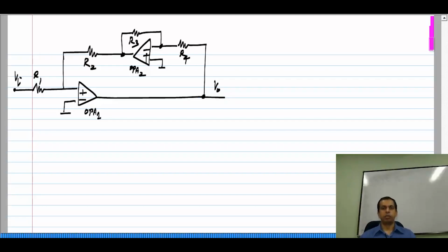And finally, sometimes you may have to resort to trial and error, because the op amp which you are replacing with the voltage controlled voltage source, you may not have determined its sign already. Okay. So, you have to consider both signs and then proceed. But eventually, there will be a unique solution. You cannot have different possibilities, right. For this circuit, for instance, this is the only possibility. So, if you reverse the signs of both op amps, you will find that one of the op amps will be in positive feedback. Okay. So, that is the algorithm in short, and you can use this for any circuit with multiple op amps. Okay.